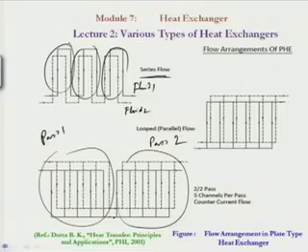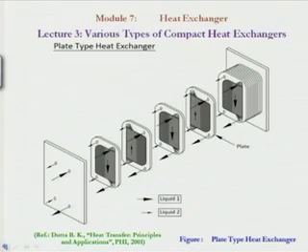and this is very important in case of plate type heat exchanger. We should understand the flow pattern. So in the first diagram that I have shown here, a similar kind of behavior is also taking place. You can see that the parallel things are happening like this. Okay, so it is a parallel flow and they are looped into this and they are going out.